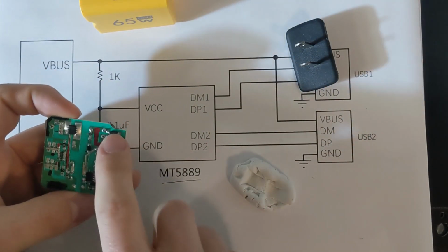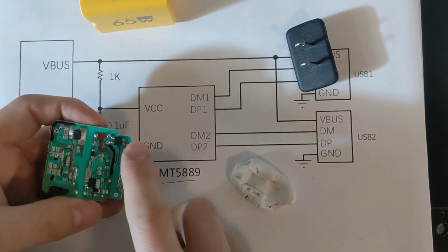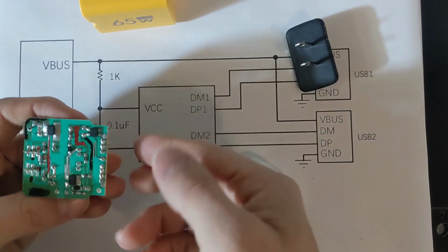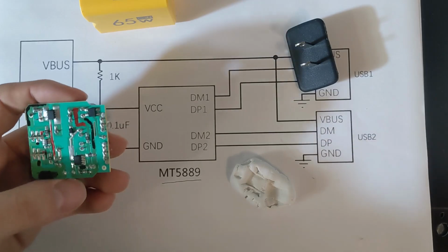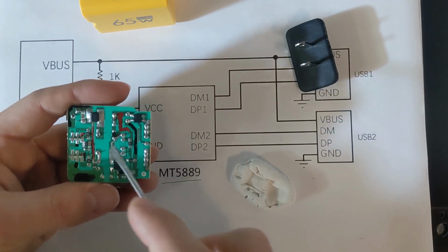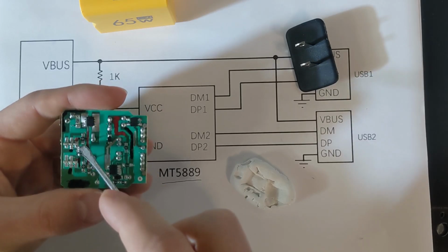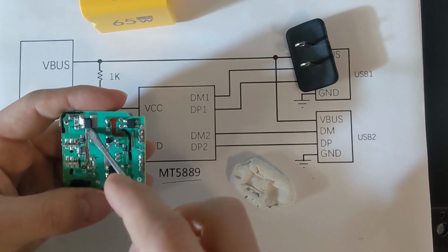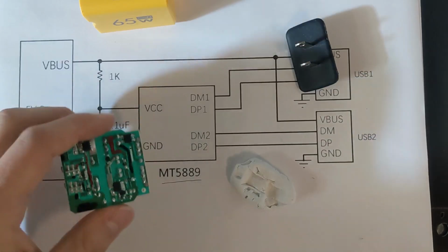You got the AC to DC rectifier bridge. It doesn't have to be very big because the currents are low, because you got 120 volts coming in. And then you've got this chip here, which is your flyback chip, and I'm going to show you that. And then this is your communication chip right here. This little tiny deal. And this, I think, looks like your rectifier. So let me show you that.